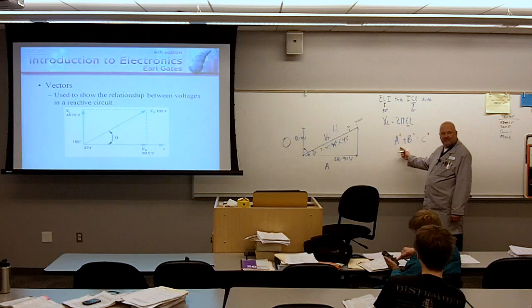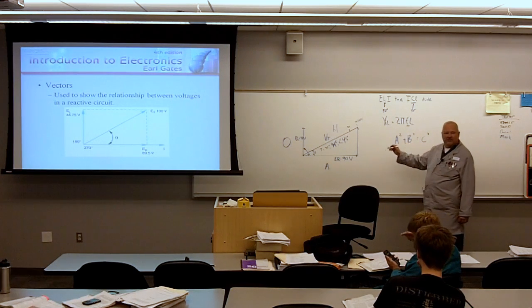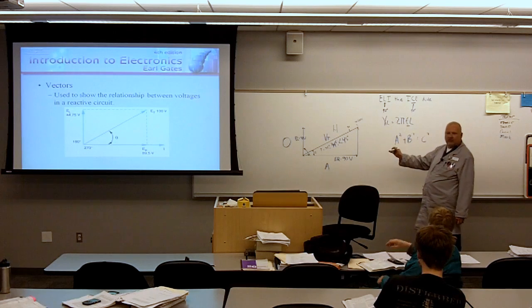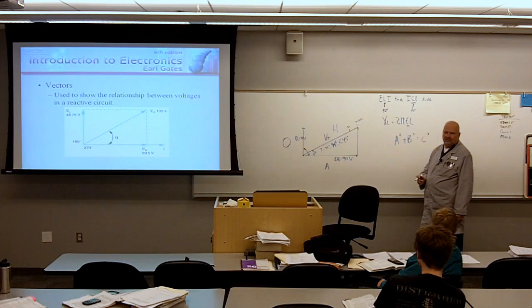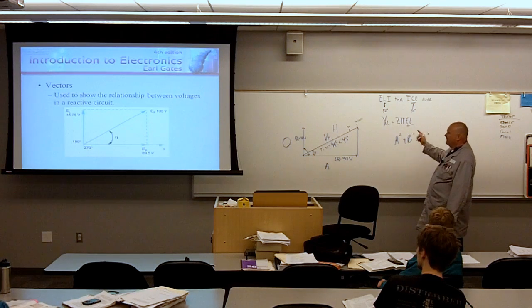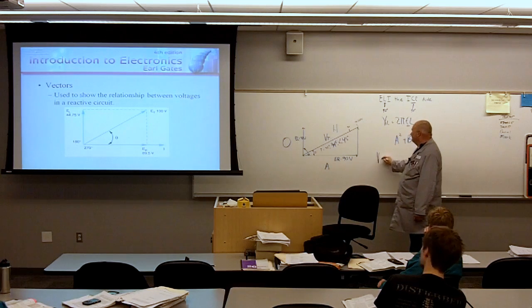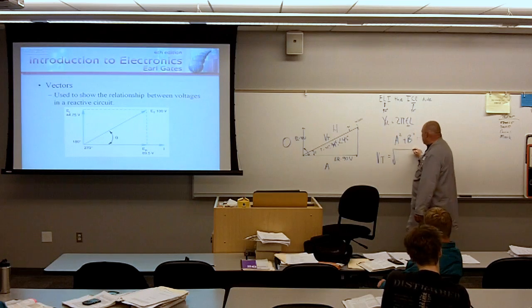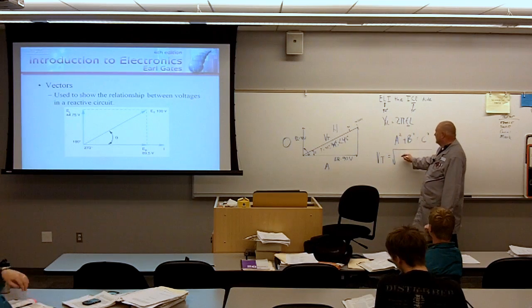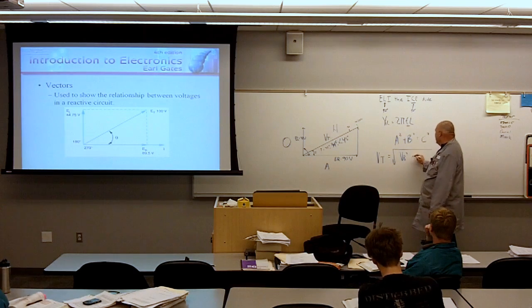This is the Pythagorean theorem. Now, we know that what we could actually do is replace these values with electrical values. And that's what we're going to do. Using algebra and reorganizing this formula, we're going to calculate that voltage total is going to be equal to the square root of the voltage of the resistor squared plus the voltage of the inductor squared.